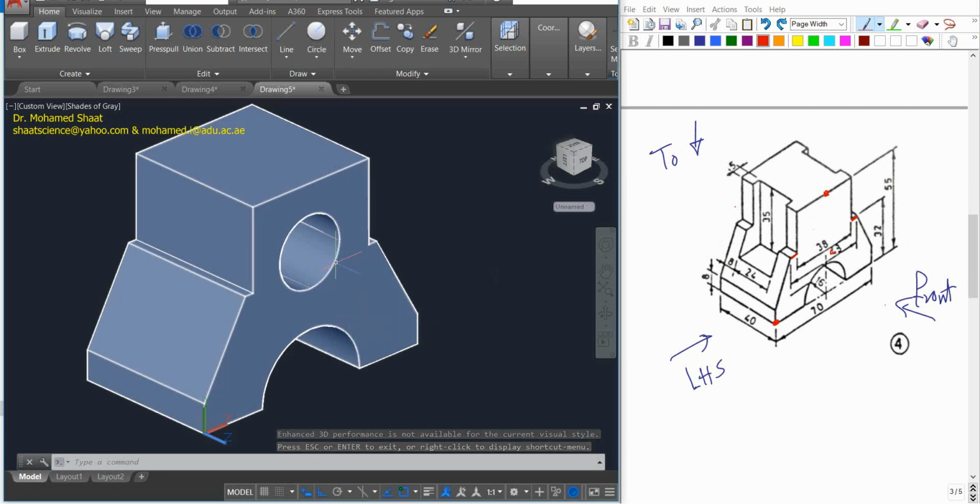This is one of the things. Press Pull is very effective when you have multiple loops, either not intersecting or one inside the other, and one of these loops represents a hole or opening in the shape. Your objective is just to click between them. Don't select one of the loops. It works a little differently than Extrude.